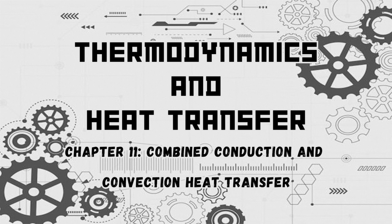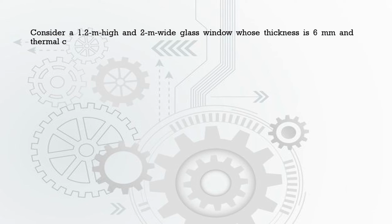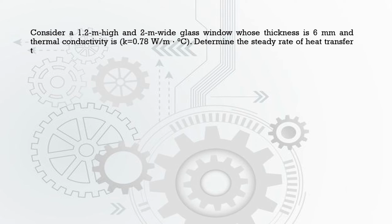Hello guys, today we're going to solve a sample problem in Chapter 11 of Thermodynamics and Heat Transfer, the combined conduction and convection of heat transfer. The sample problem is, consider a 1.2 meter high and 2 meter wide glass window whose thickness is 6 mm and the thermal conductivity is 0.78 watts per meter degrees Celsius.